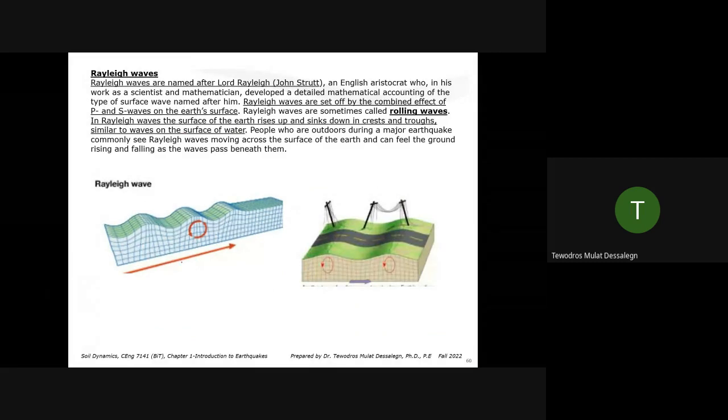Rayleigh wave, this is a surface wave. Now we are on the ground surface. A person can really stand on this and feel how the wave is traveling underneath. In the surface wave, if your motion is like this, up and down, it feels like the local particles are moving in a circular direction, like a rolling, and the ground feels like undulating like this. So in that case, that's a Rayleigh wave. It was first discovered by a person called Lord Rayleigh. I think he's an English aristocrat. So if you have telecommunication cables or power cables on the ground, this is what a Rayleigh wave can cause. Wherever it's going up and down, you can see ground cracks, or the cables being broken apart.